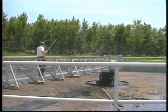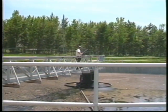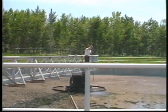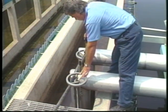In any event, the activated sludge is removed from the clarifier by means of the sludge collection mechanism that may utilize pumps, airlift, differential head, or a siphon mechanism to remove the activated sludge from the clarifier.